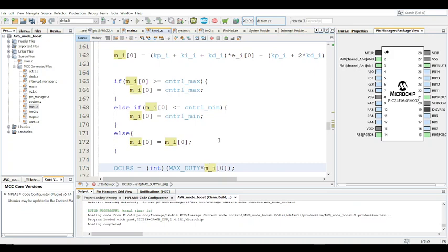Usually, from all the calculations that I've seen in textbooks, that's all they do. They base it on the maximum duty being 1. So you have your 1 there, and then you have the max duty of the actual microcontroller, what it actually sees, which is in this case 159.